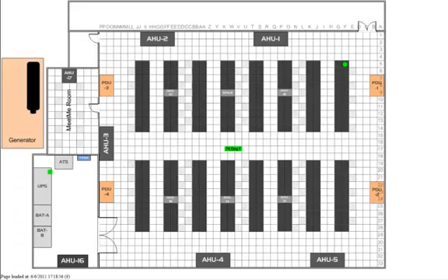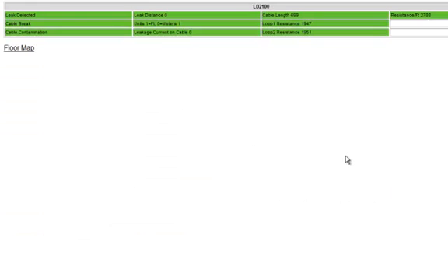At this point we're going to go out on the floor and we can generate alarms at our different equipment, verify our analog values are correct. Right now we're generating an alarm on our UPS. We can see that the green block has changed from green to red, showing us the change of status. In the middle we can see our analog sensor showing the value and the unit of measure, and then we go up to our Modbus point and see that everything's normal. When we mouse over the Modbus, you can click on that circle and it will show you all the registers or OIDs assigned to that device.